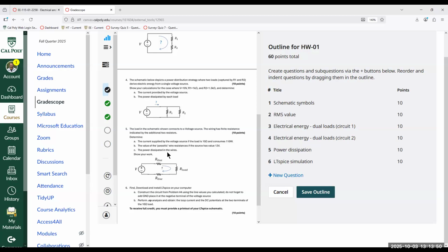When we perform a calculation on this one, the current flow is shown. If it's not shown, the way we would determine it is from a source: current always goes from minus to plus. Meaning for this voltage that we see in here, current is going in the upwards direction. If it goes upwards, there is no other place for it to go except from left to right and then make a loop. So as shown in the circuit diagram, the current is flowing clockwise, right?